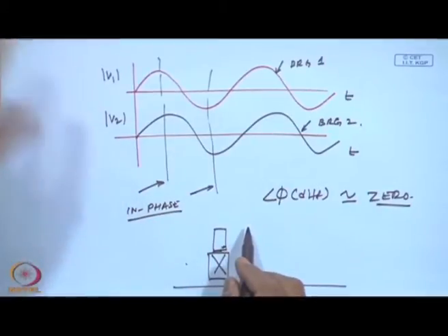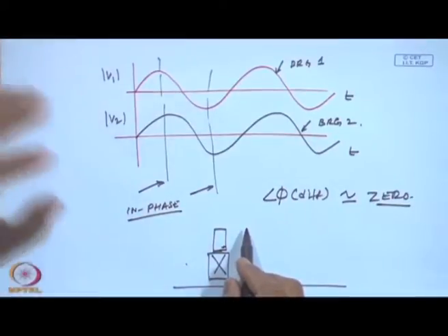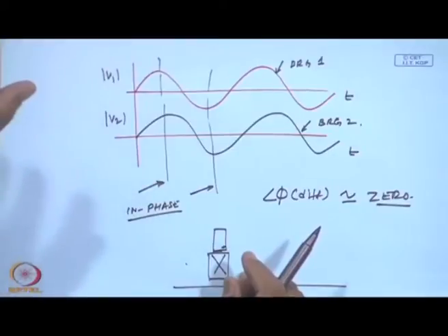So, these are the diagnostic techniques or routines which we have to follow to ensure that it is unbalance and not looseness or misalignment or a cracked shaft. These are the processes by which we can be sure that yes, there is an unbalance, because I am having a high radial vibration compared to the vibration in the axial direction, and then of course, the vibrations between the two bearings are in phase, or at 0 degree.